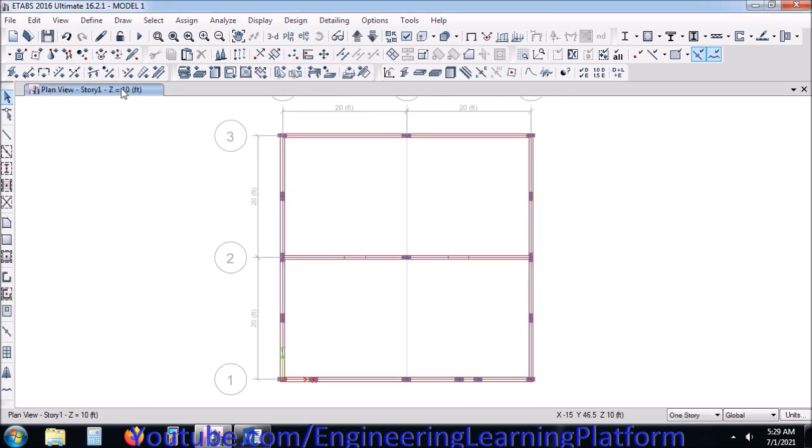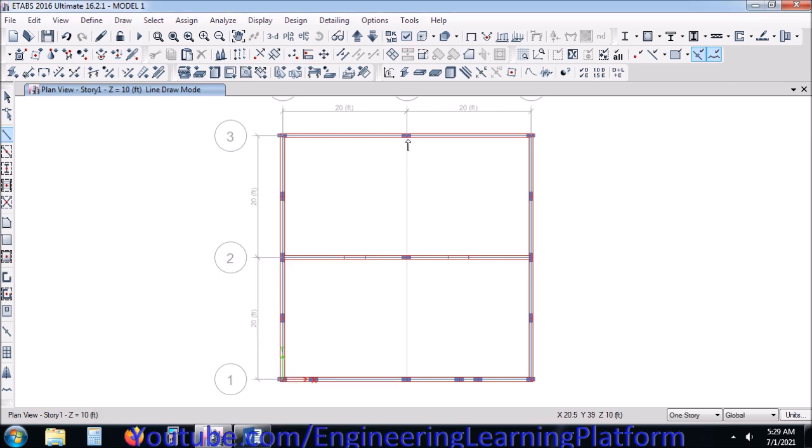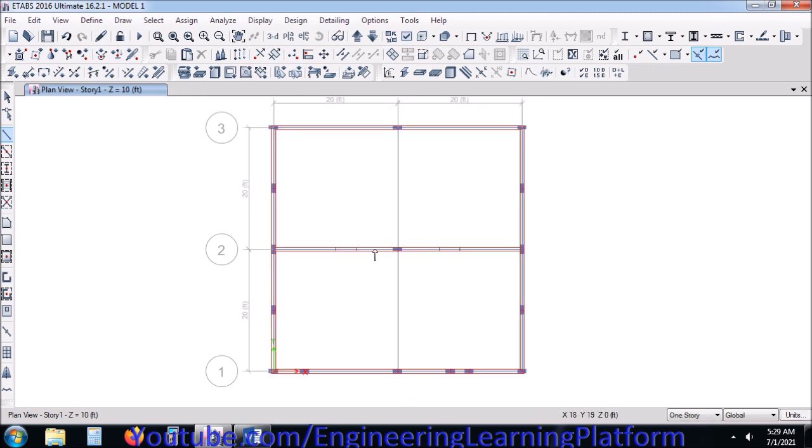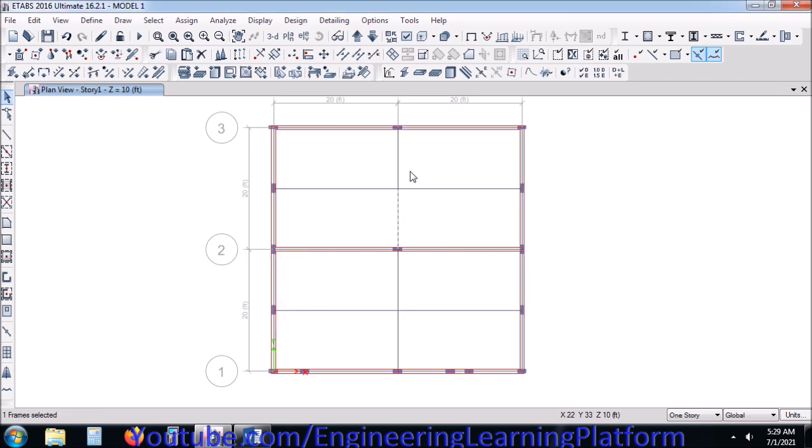So I'll be adding more reinforced edges or reinforced areas in the wall, and I'll further add beams in the structure so that the stress is properly distributed on the beams and a transfer mechanism between beam and the reinforced edges is formed, rather than all the stresses going to the walls alone.